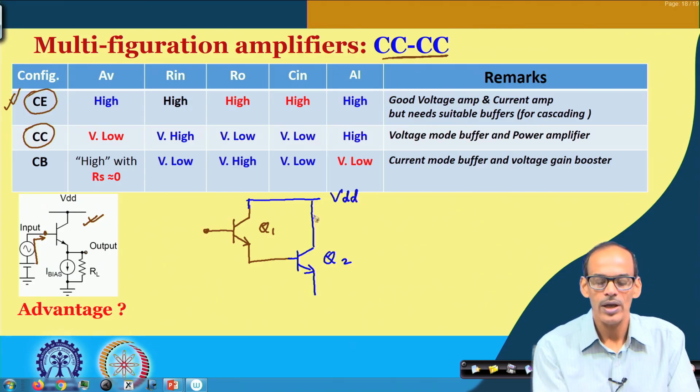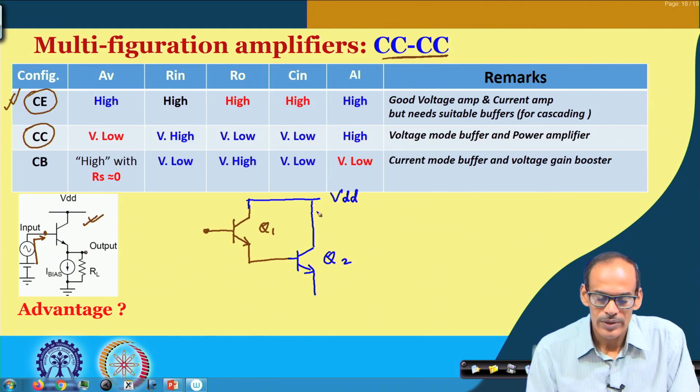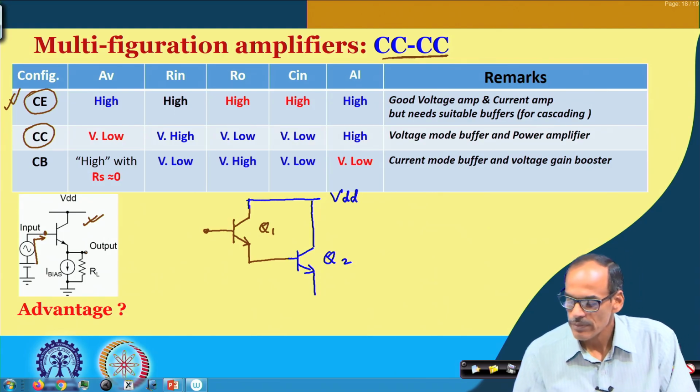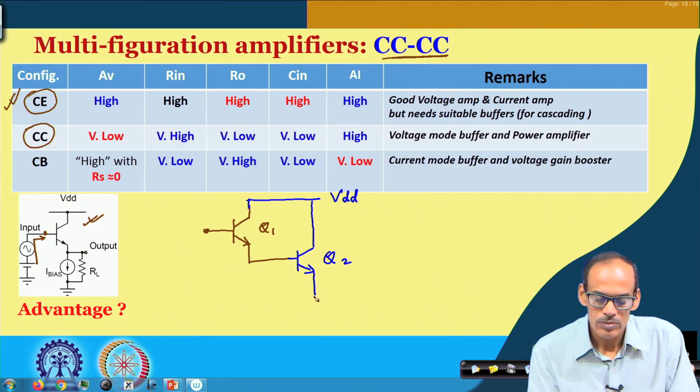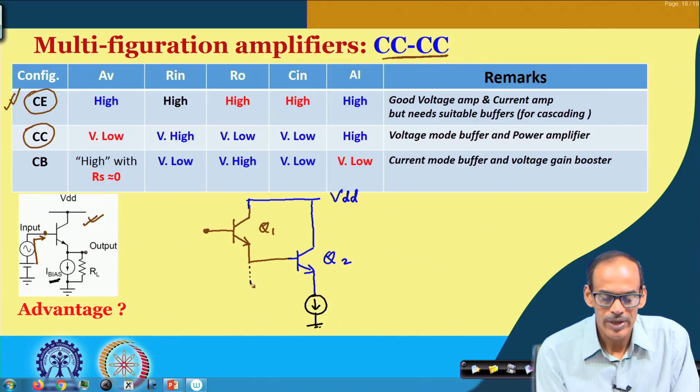In fact, we can have some resistance also connected there, but for the ideal condition we want that. And if you see their bias conditions, we may think of a DC current here, and we may or may not require this DC current depending on the level of the current of Q1 and Q2.